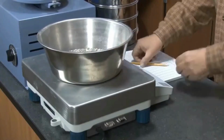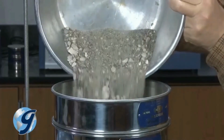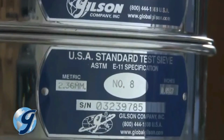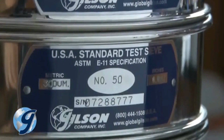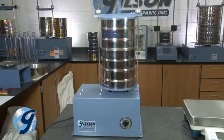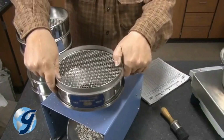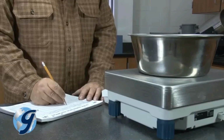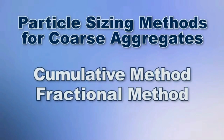A dry representative sample of material is weighed and then is placed in the top of a group of nested sieves or screen trays, arranged in descending order from the largest openings at the top to the smallest at the bottom. The stack is agitated manually or using a sieve shaker for a designated period of time, and the operator weighs the material retained on each sieve